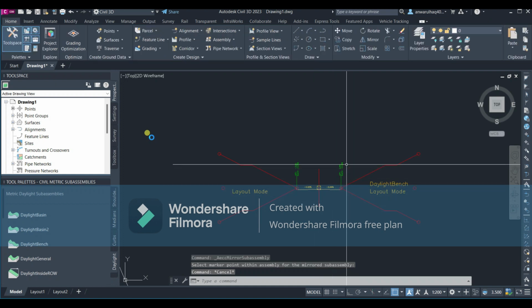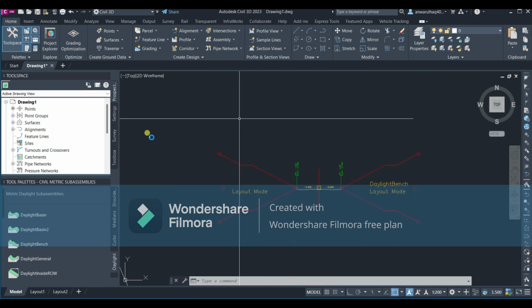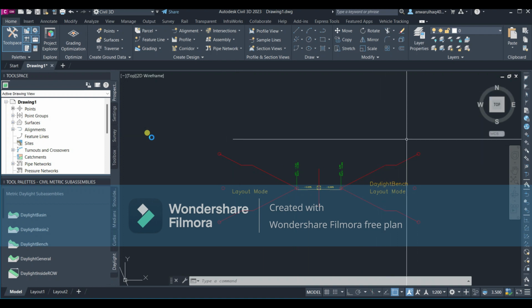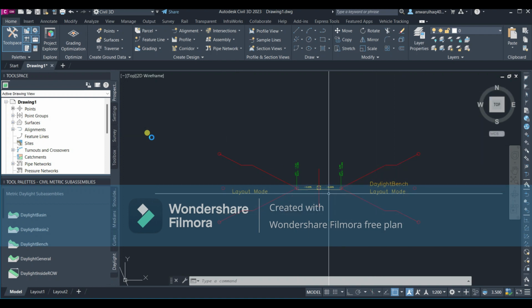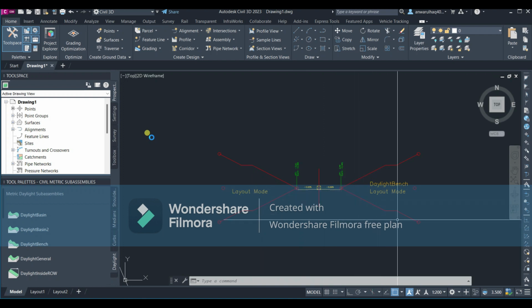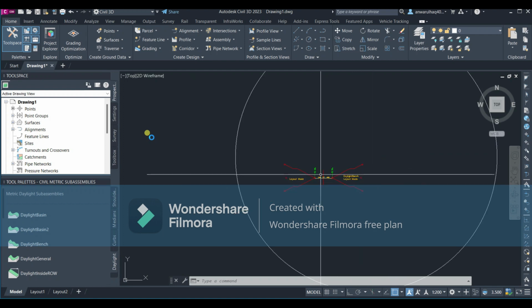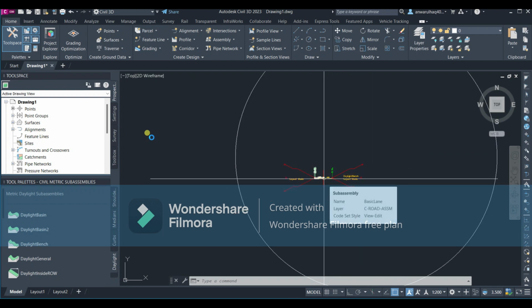Okay, so now both my ends are completed, because this also provides the daylight, which will follow up to the ground level or up to the earth. If the earth is below this road level or this point, this profile will be above the natural surface level, so the daylight will follow downward. If the natural surface is upward, the daylight will follow upward. So this is completed for our cross section.